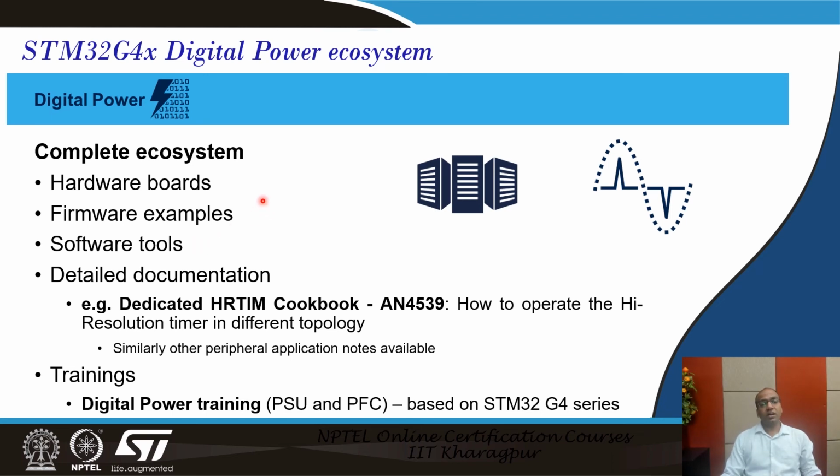Also, there are several hardware boards like STM32 Nucleo boards, discovery boards, and evaluation boards. There are several firmware examples developed for STM32 Nucleo boards and discovery boards. Evaluating those examples not only assists in understanding the peripherals or the application working, but also reduces the time of final product development.